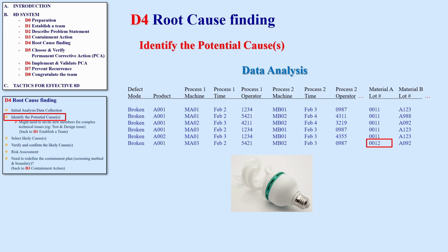We have to understand, the actual world is not perfect. Even if we only use so-called good material, we still tend to see some failures from time to time. We see these as random failures. The last bulb might be a random failure, part of the normal fallout. This kind of data point might mask our data and cause some confusion in finding the commonality, especially for junior engineers. Commonality analysis is one of the powerful techniques to identify potential root cause.